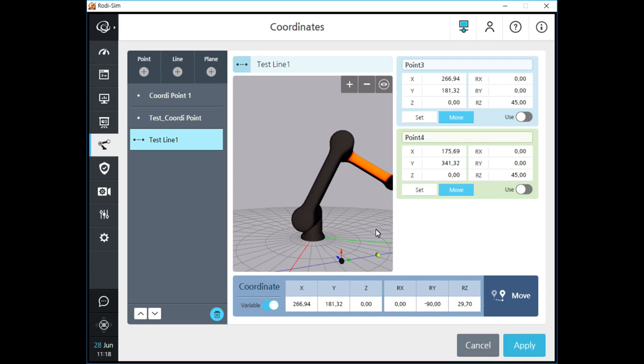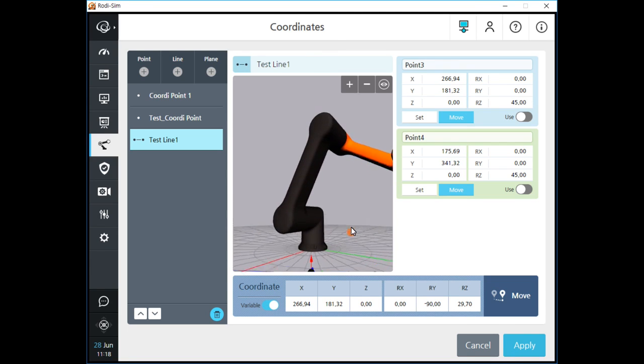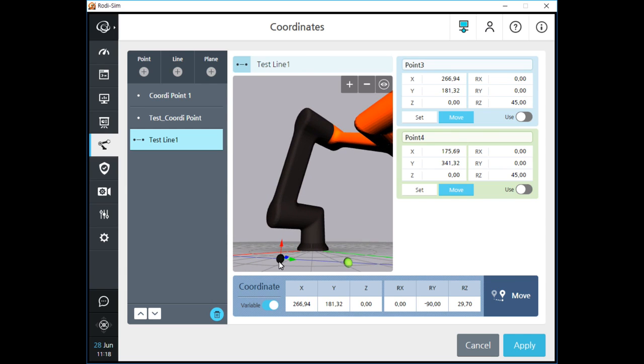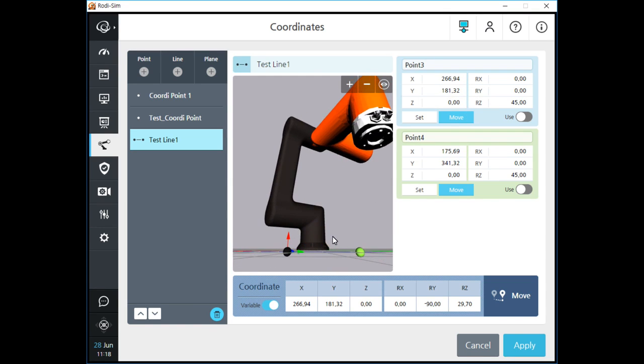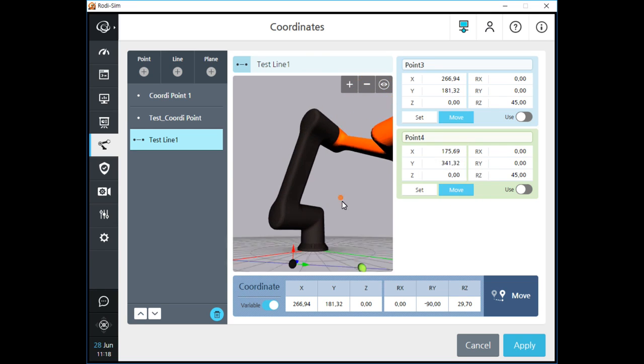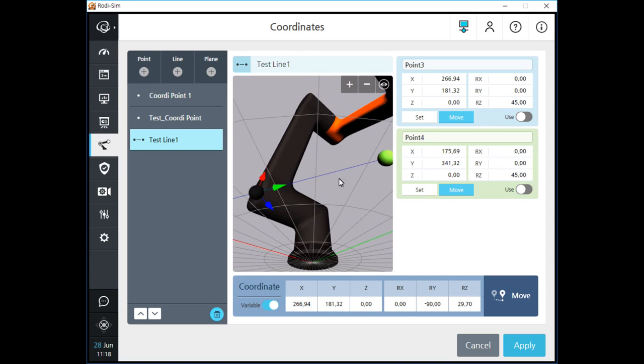After you click the OK button this time, you can see your new y-axis on the screen in blue color. The black sphere is the origin of this coordinate, and the positive direction of the y-axis is the same as the direction from the first to the second waypoint. In this line type coordinate, it's hard to get precise x and y axes as you want, so I recommend you use this type when you need a specific direction. I usually use this line type coordinate for manual control mode, not for modifying the move commands to copy and paste.